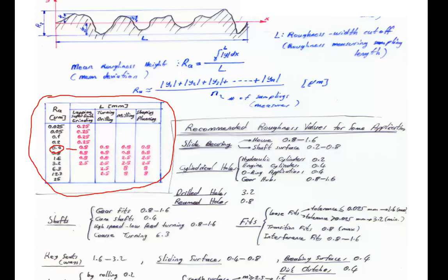If the measured roughness size is close enough or equal to the roughness size you guessed at the beginning, then it is okay. No need to repeat the experiment. But although in your guess you said 0.4, when you measure the roughness size you found, for instance, 3.2, then repeat the experiment.